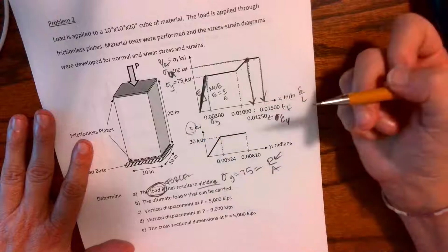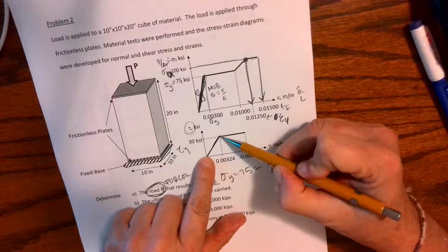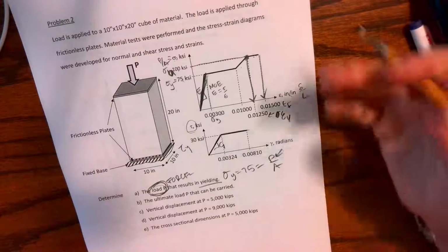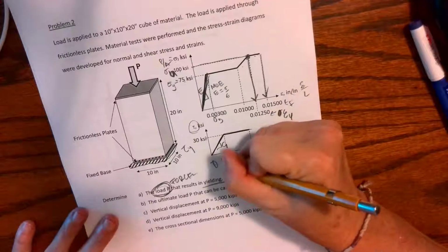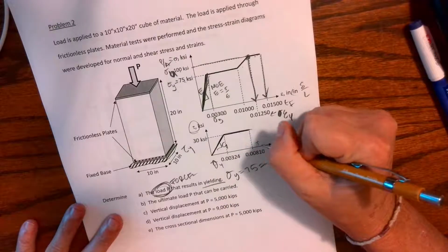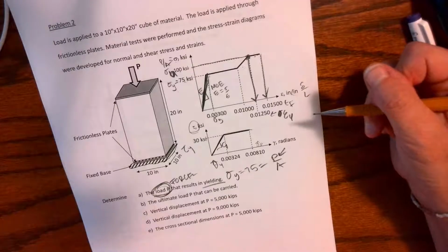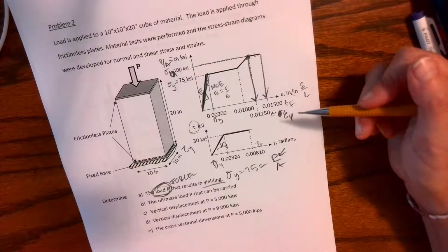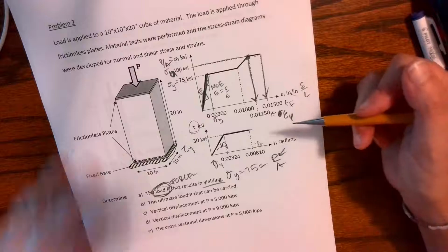Here is my shear. I have a yield. That's where I get out of the elastic region. We now have that yielding. This is G, my shear modulus. It's just the slope of that line. This is the shear strain associated with yielding. And here's my shear strain associated with fracture. Okay? And I just need to be able to understand the definitions. Okay? I just have to understand definitions.